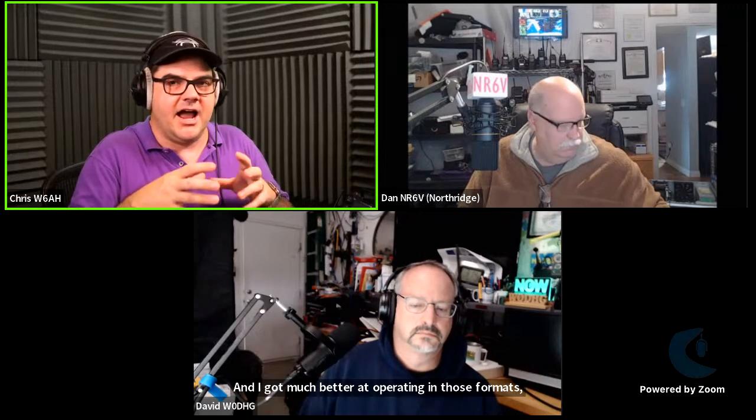Did it work great? No. Did I make contacts on it? Was I able to talk to Alaska and all the way across the US and have NVIS communication and communications all over California with it? Yes, it totally worked. The trick that I found when I was in that situation, I started by spending more time doing digital modes like FT8, and I got much better at operating in those formats because of the living conditions that I had. And then I would go do voice and other types of HF in a portable setup.